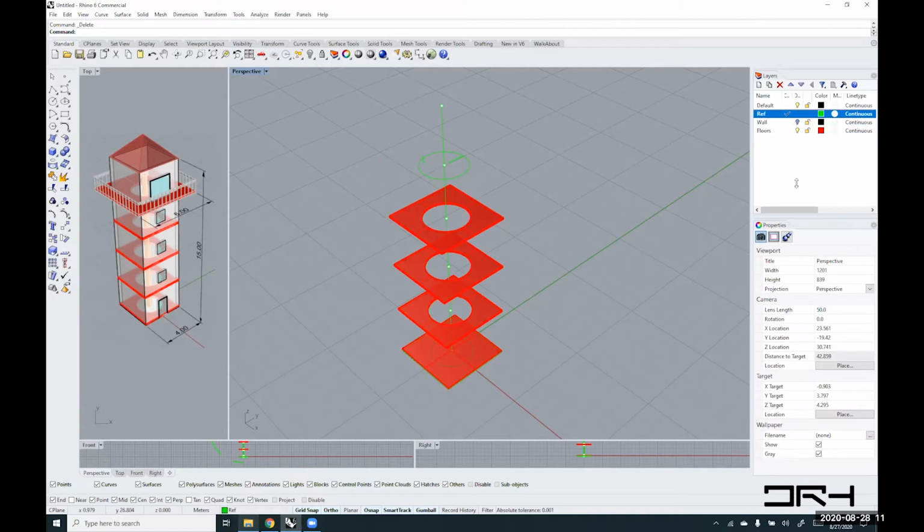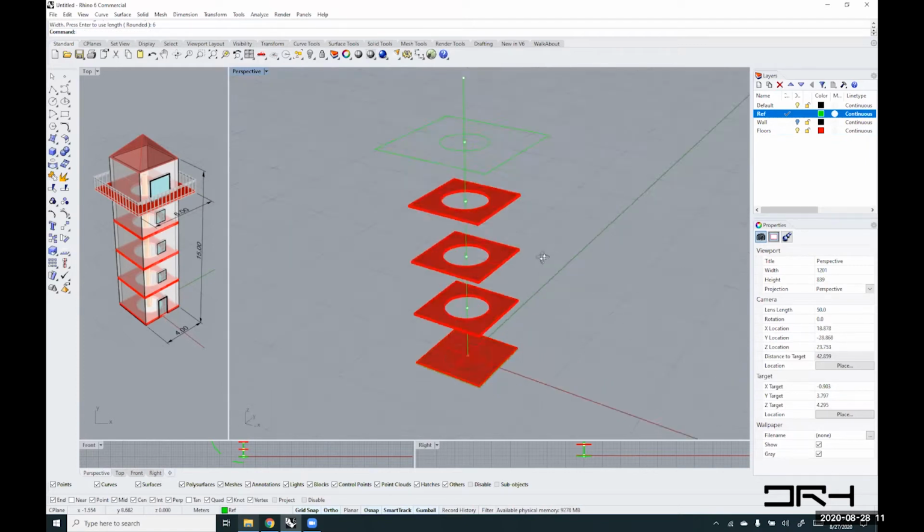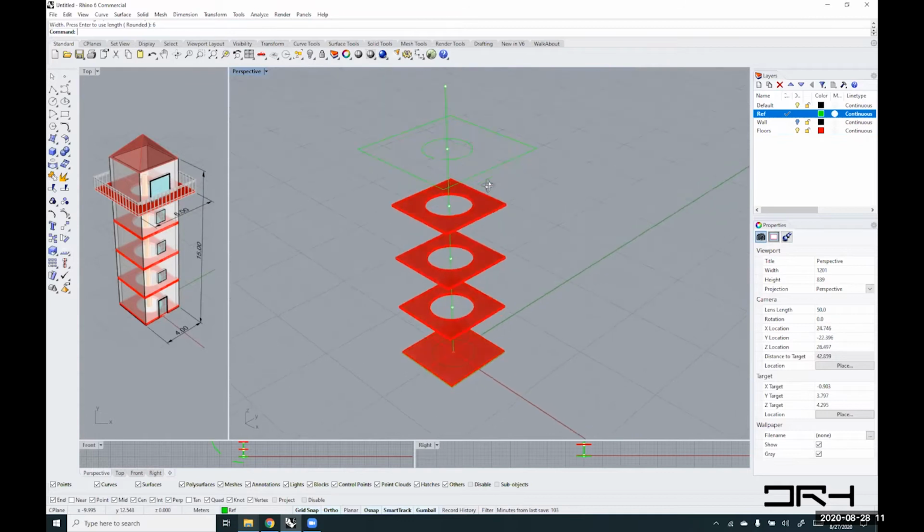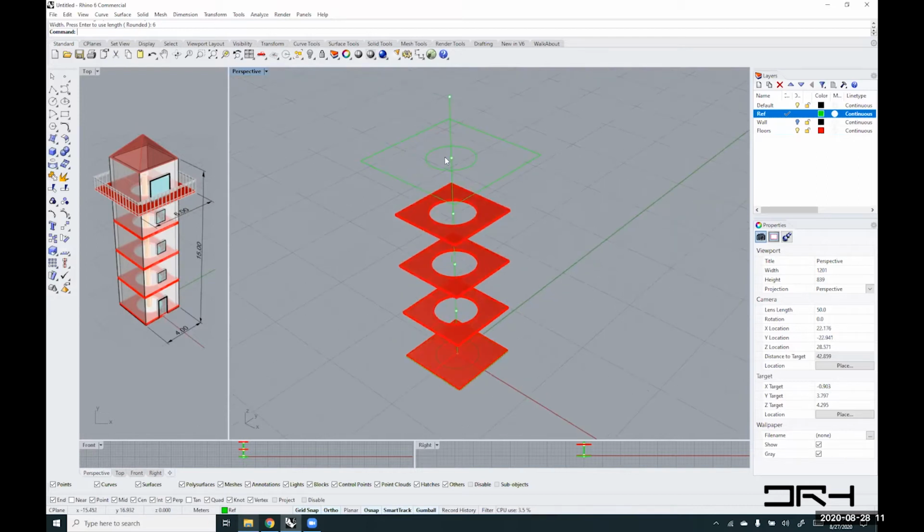Go to my reference layer and say rectangle, and I'm going to snap to the point, and then, oh, I should have chosen center. So center, snap, and then it's going to be 6 by 6. So I'm going to type 6 and then 6. And remember, all geometry is created parallel to your active C-plane. My C-plane is the world top C-plane, and since I snapped at some elevation, the rectangle will continue to fall in a plane that is parallel to that. So now I've got my rectangle and the circle, and I'll go to my floors.